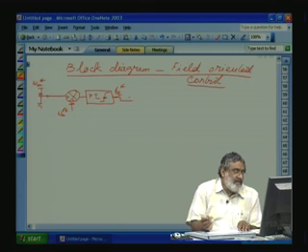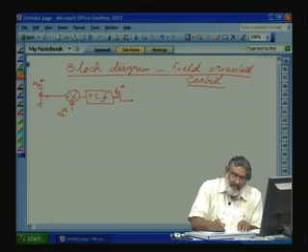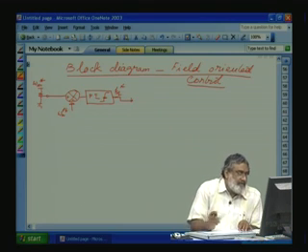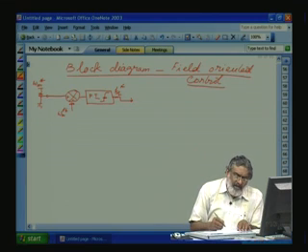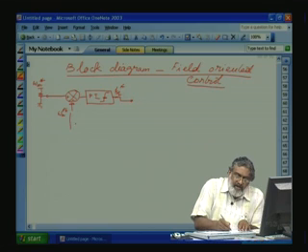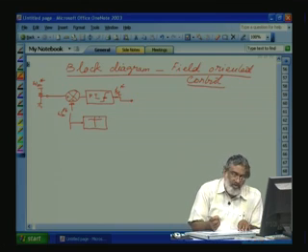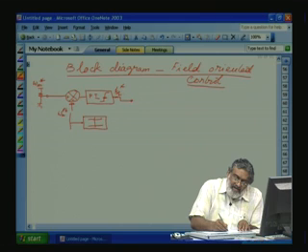This ISQ reference, we got it. Now let us say speed feedback. If you give the speed feedback, till base speed it will make our ISD constant. After that, in field weakening, it will make it inversely proportional this way. So we have a lookup table here. This is our ISD. ISD is equal to IMR.